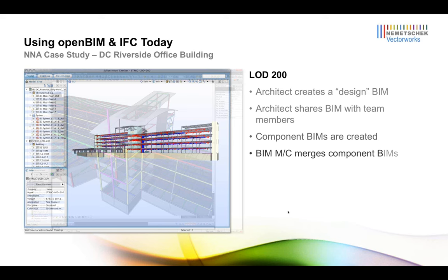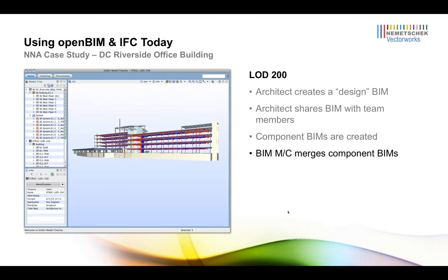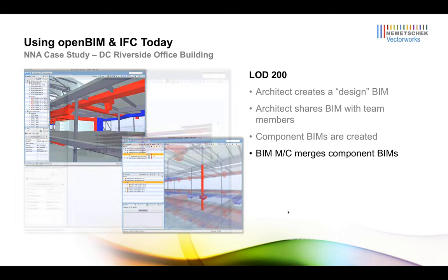And so everybody creates their IFC exports, and the BIM manager coordinator takes these components and is able to merge them and do things like clash detection, right? And then report on this clash detection or data verification, and distribute these models and reports back to the designers for resolution. That isn't to say the designers couldn't be doing it among themselves, but with a BIM manager coordinator, you have somebody that ensures that the right data is going in the right direction at the right time, right?